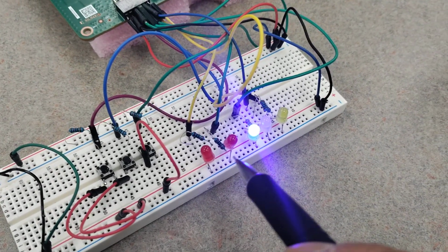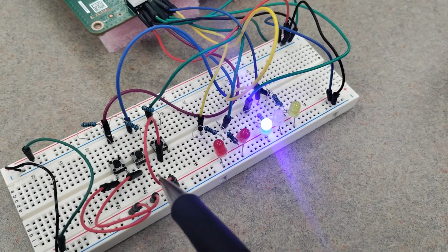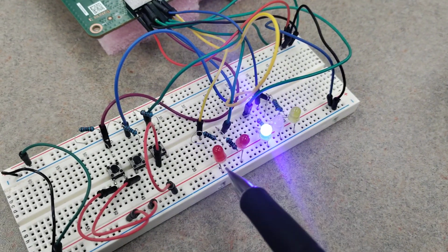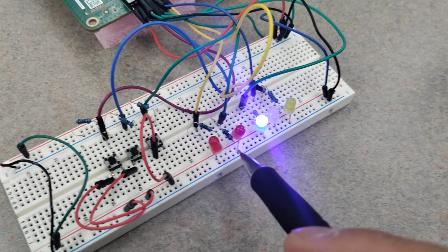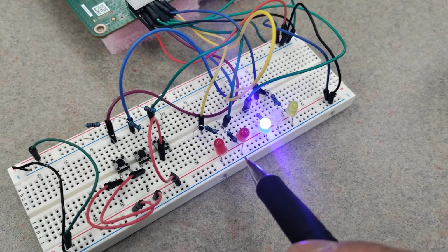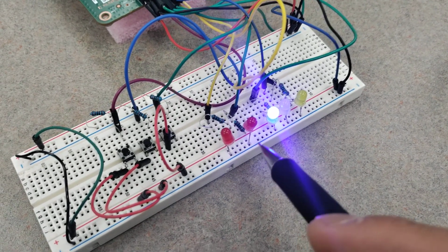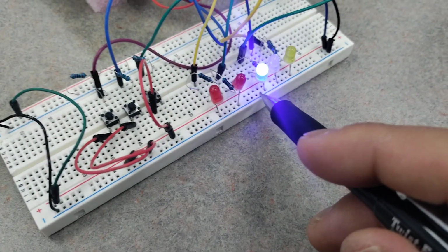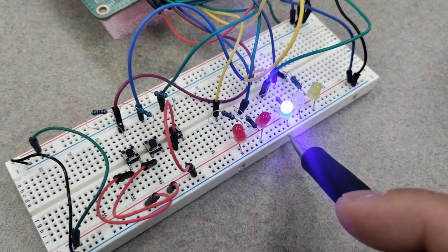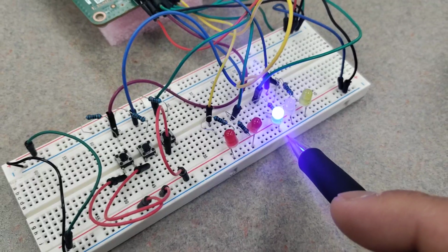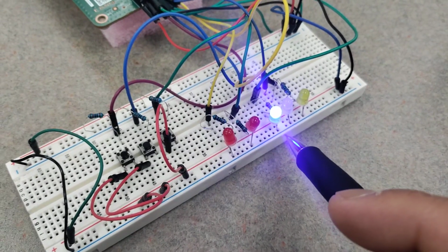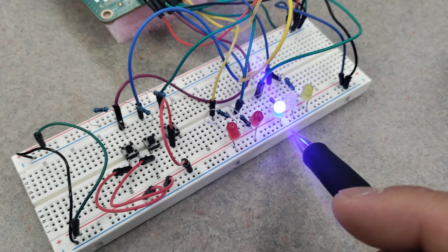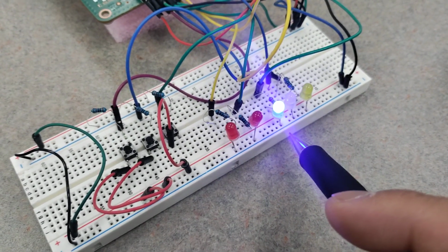And then we have these 5 output LEDs. So the buttons represent the input, and the 5 output LEDs represent the output. These 2 LEDs here, the first 2 red ones on the left side, represent our binary representation of the floor that we want to go to. And this blue LED, the one that is staying on, represents our door that remains open at all times. So by default, when you run the code, the blue LED will stay on and it will remain on as long as the program is running.